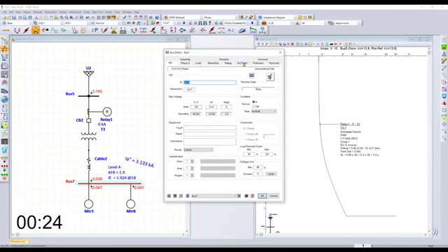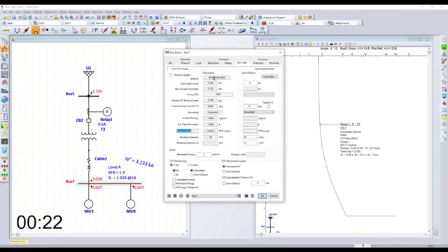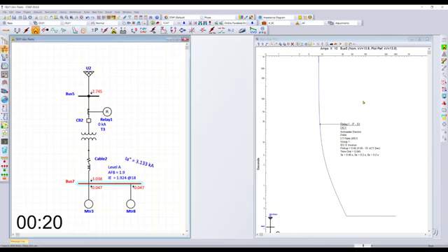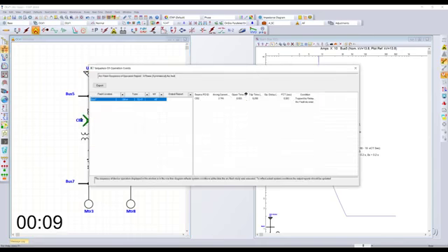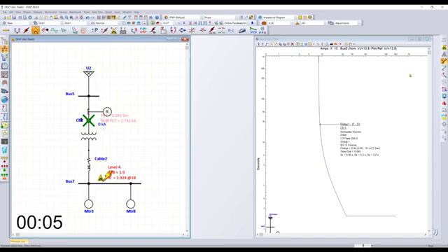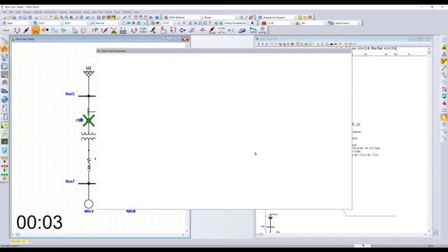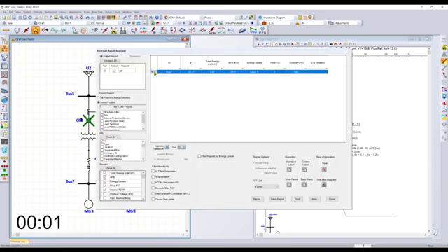So from here, you're ready to go to the arc flash page, see more details, or go inside the sequence of operation for arc flash, and you can investigate in more detail what's going on inside this network, who's tripping and at what stage. And once you're happy with that, you can simply go inside the arc flash analyzer, and from here you also have the possibility of printing labels, work permits, data sheets, and a whole lot more.